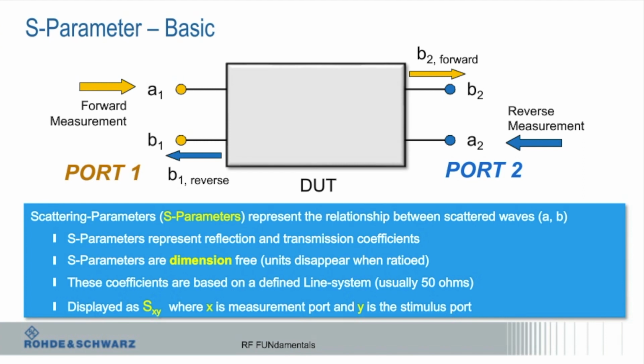Guys who are, for example, characterizing components, generating S-parameter modeling files, really want utmost accuracy. Those guys will typically calibrate at a more frequent interval, but the best thing to do is to have a verification device. We actually make verification kits, but it doesn't have to be a verification kit; it's basically a device with a known S-parameter file or set.